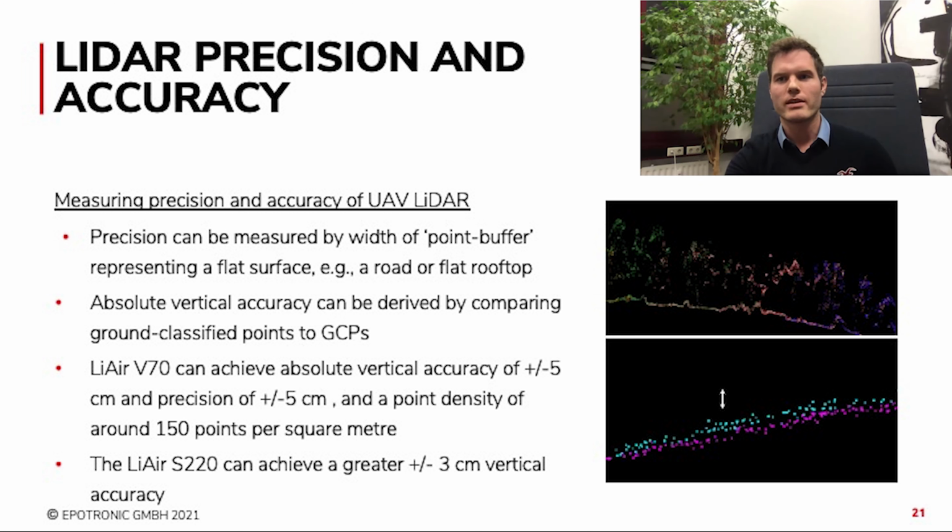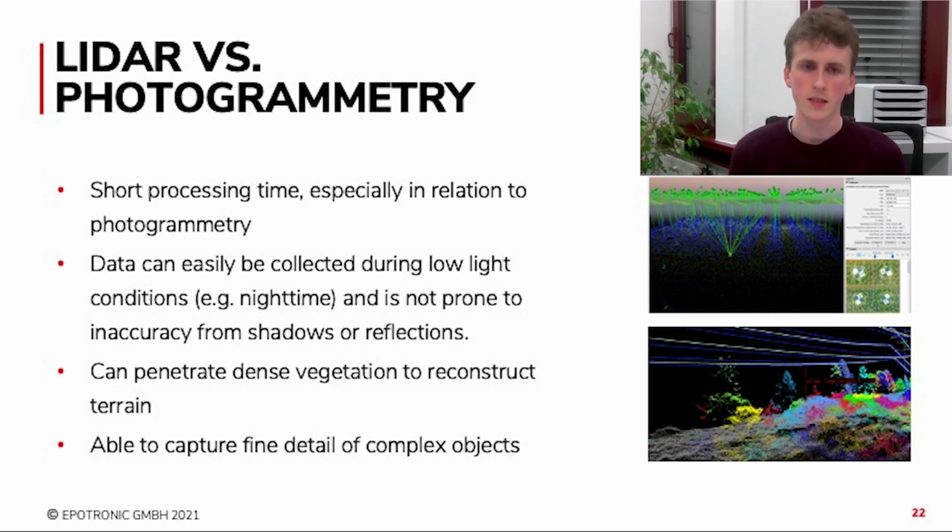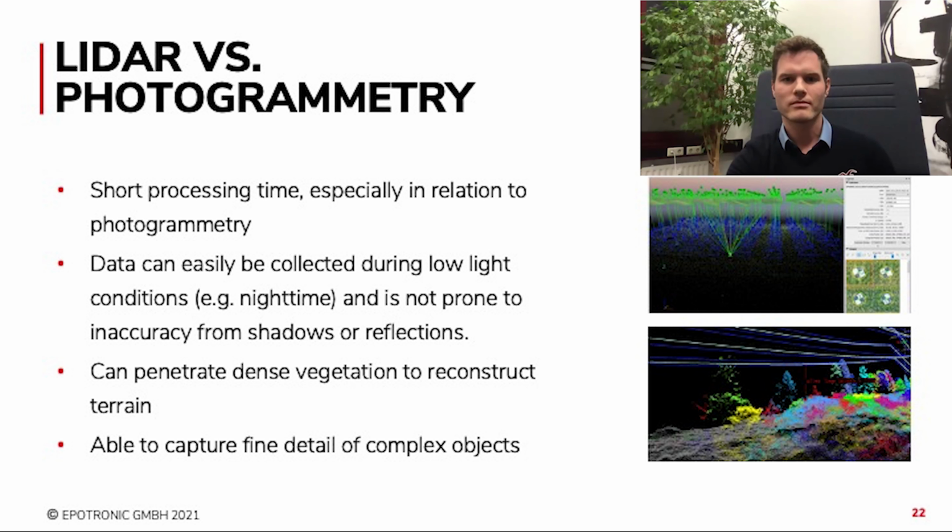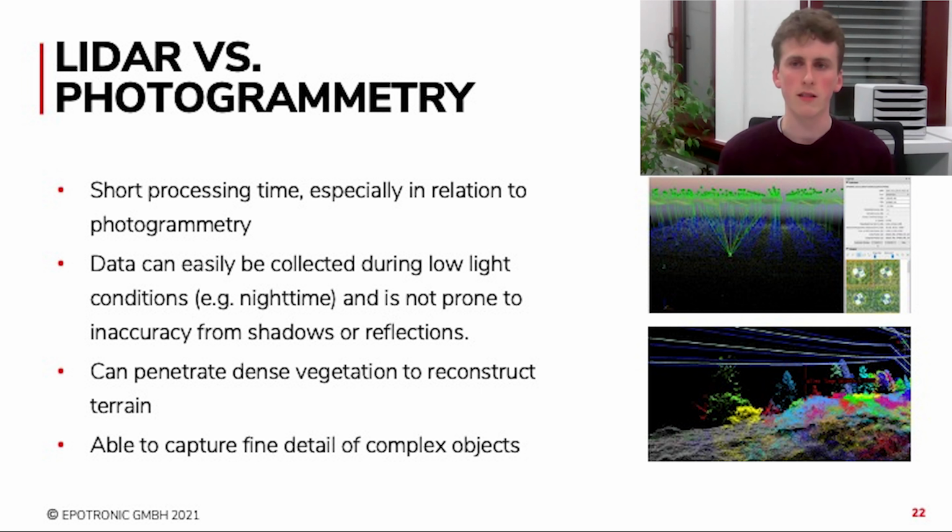So moving on, a question which might be quite common is, what are the advantages of UAV LiDAR compared to photogrammetry, especially considering the setup cost? One of the big advantages is the processing time. With LiDAR, processing takes about 20 minutes, 10 minutes even for a small survey area, because the point cloud is captured directly. With photogrammetry, it has to be generated from the images, so that could take hours, days potentially. And that reduces the amount of surveys that can be done if you're limited on the number of processing computers you have.